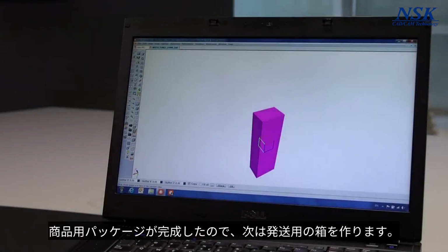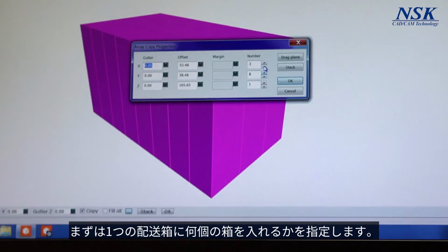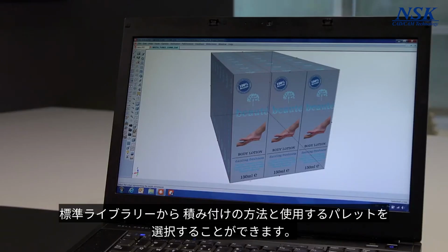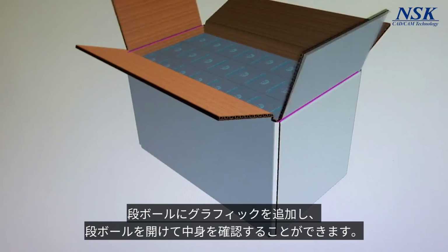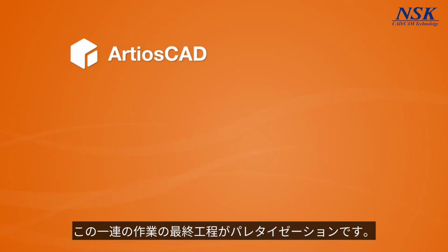Now that our single pack is finished, we will create a shipping box around it. First, we indicate how many cartons we want in one shipping box, 8 by 3 for instance. From our standards library, we can choose the style of shipper and the board to be used. We add some graphics to the shipper, and in opening the corrugated box, we can see the content inside. The final step in this sequence is palletization.